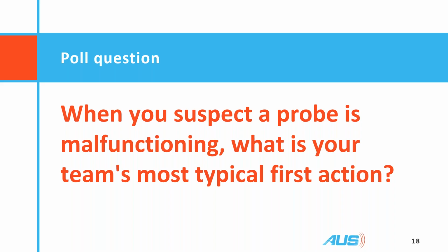If you're familiar with ultrasound, in-house testing is by far the easiest. One of the things that we teach in our classes is multiple ports and multiple probes. And what that means is if your probe's not working in one port, try moving it to another port on the system. If you have a full-size system with multiple ports, try using it in a different port and see if the image quality changes. It could be a port problem.